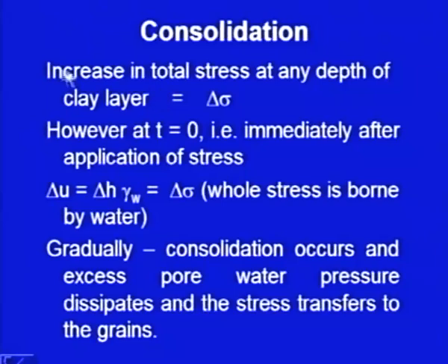So, the increase in total stress at any depth of this clay layer will be delta sigma. This is the total increase. Just in the beginning, theoretically at time t equal to 0, immediately after the application of the stress, the increase in pore water pressure, the excess pore water pressure, will be equal to the total stress which has been applied at the top.